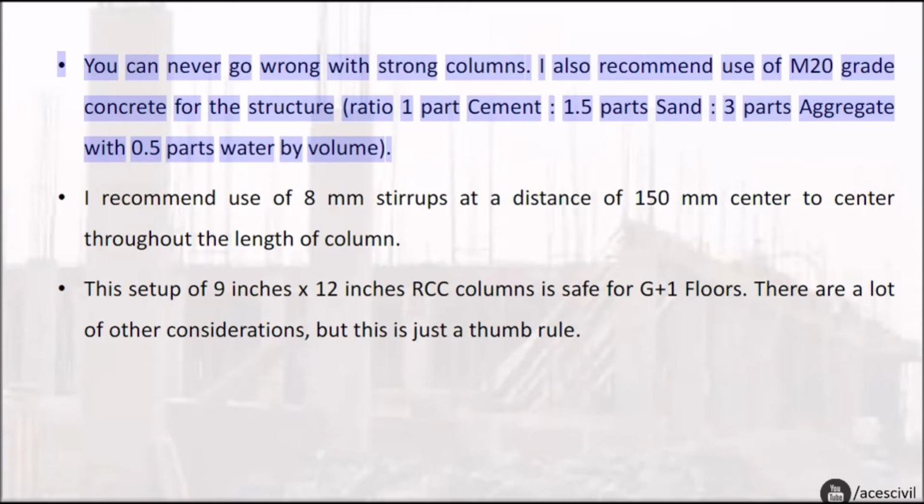I also recommend use of M20 grade concrete for the structure, ratio 1 part cement, 1.5 parts sand, 3 parts aggregate with 0.5 parts water by volume.